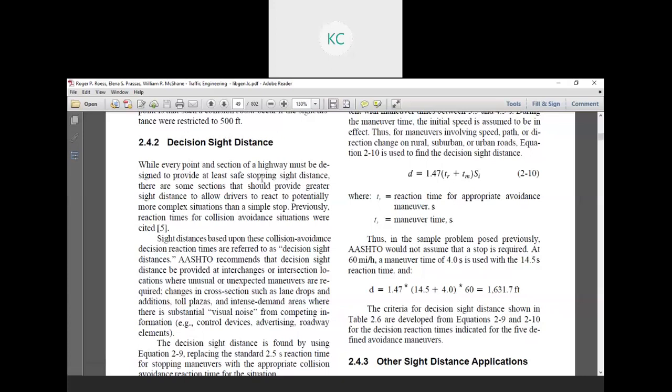So it is recommended that a particular sight distance be provided for a highway or class of highway, like the national highway or state highway, but in that particular vicinity a greater sight clearance or safe stopping sight distance is required, like at an intersection, because there are a high number of merging and diverging lanes.